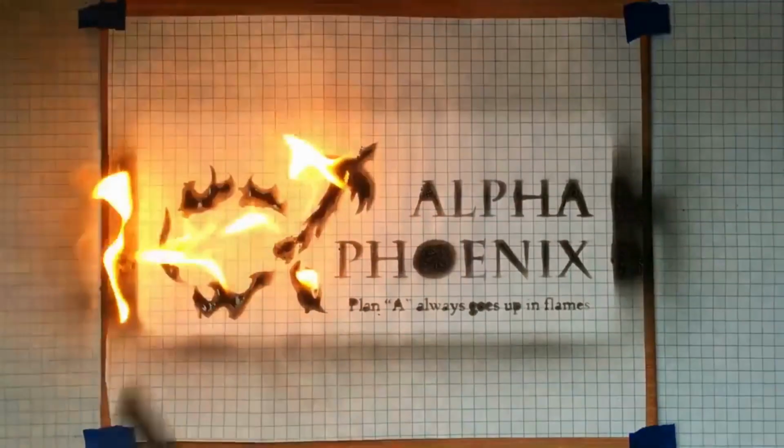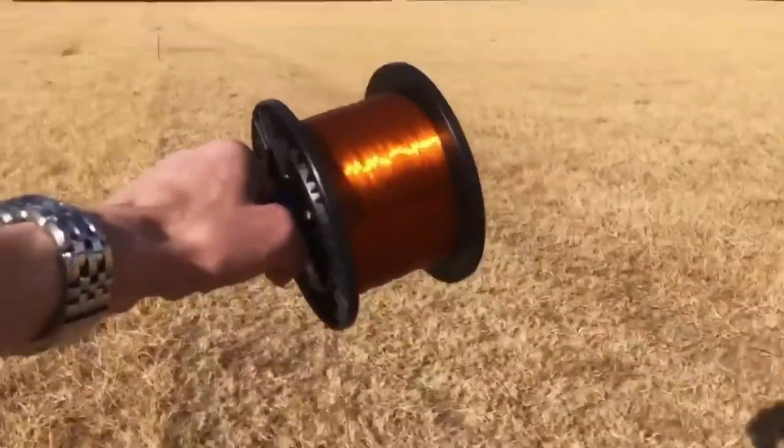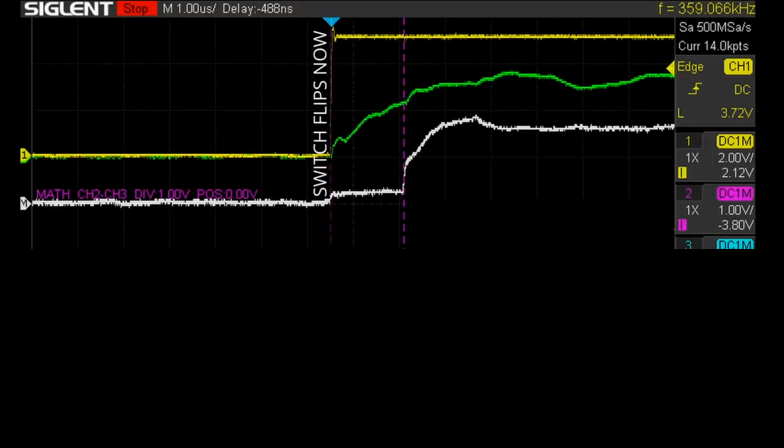Some insight can be gained from the channel Alpha Phoenix, who ran a small-scale experiment with about 1 kilometer of wire. His basic setup is shown in this diagram, with the important takeaways being that A, the white probe gives the voltage across his light bulb, and B, that he has about 1.6 microlight-seconds of wire between his switch and the bulb. Here is the output from his experiment, and covering up some unimportant signals, we can see that the current across his resistor rises to 0.2 milliamps right when the switch is first flipped. And then 1.6 microseconds later, after the wavefront has had time to travel through 500 meters of wire, we see that the current rises again to 1.7 milliamps.